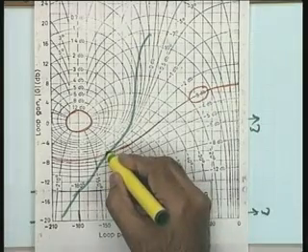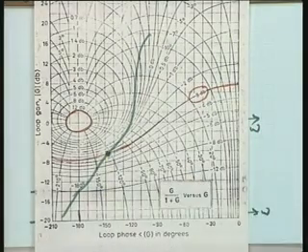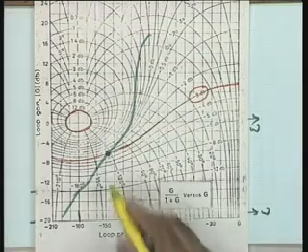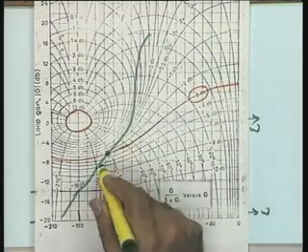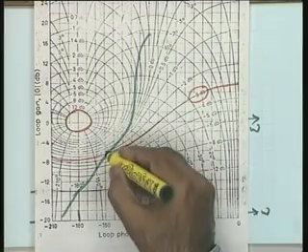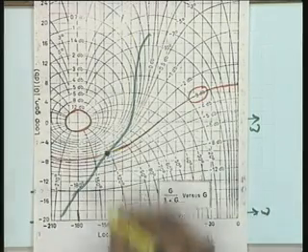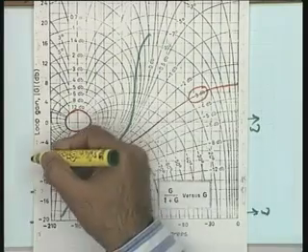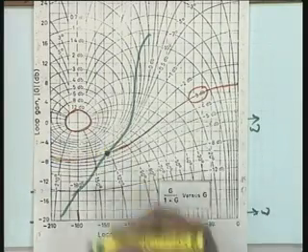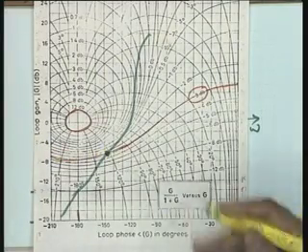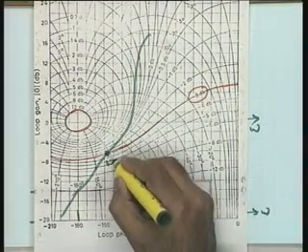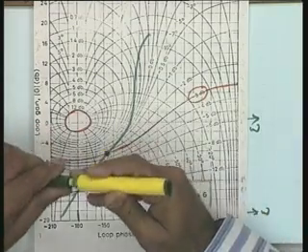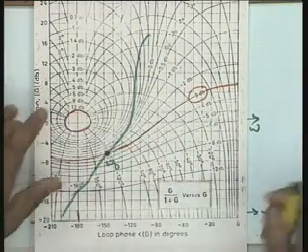See, first of all the bandwidth, which is of great importance to me. You got this point, you do not know the frequency at this particular point, fine, but reading this frequency from the Bode plot is easy, because at this particular point you have got the magnitude and the phase angle. Take one of the data, magnitude or the phase angle or both, just to verify that it works, and read off the corresponding frequency from the Bode plot. This gives you the value of bandwidth omega b. I hope you will agree that this is an easier method, and the constant M circles was simply a route.